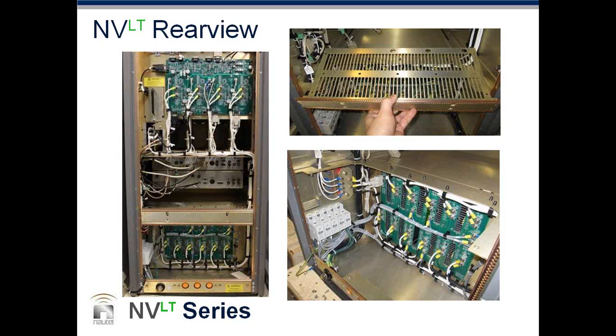And if you watch their path, they travel up the side of the transmitter and connect to another card at the top of the picture, which is where the RF power modules interface card is, and that's the DC input to those modules. Right. So in our FM transmitters, the power control is usually done through varying the DC voltage on the RF amplifiers. And so those power supplies, through a serial bus control, can vary their output DC voltage.